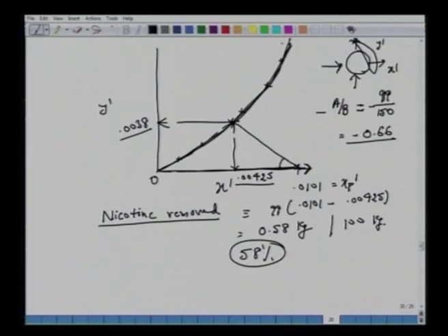Again, working graphically or writing down the equations, we have A, xf prime. The solvent was pure, so we have y double prime equal to 0. Then we have the treated raffinate, x1 prime, plus B y prime. All right, so A is known, B is known, xf prime is known. These are the two unknowns. We require one more equation.